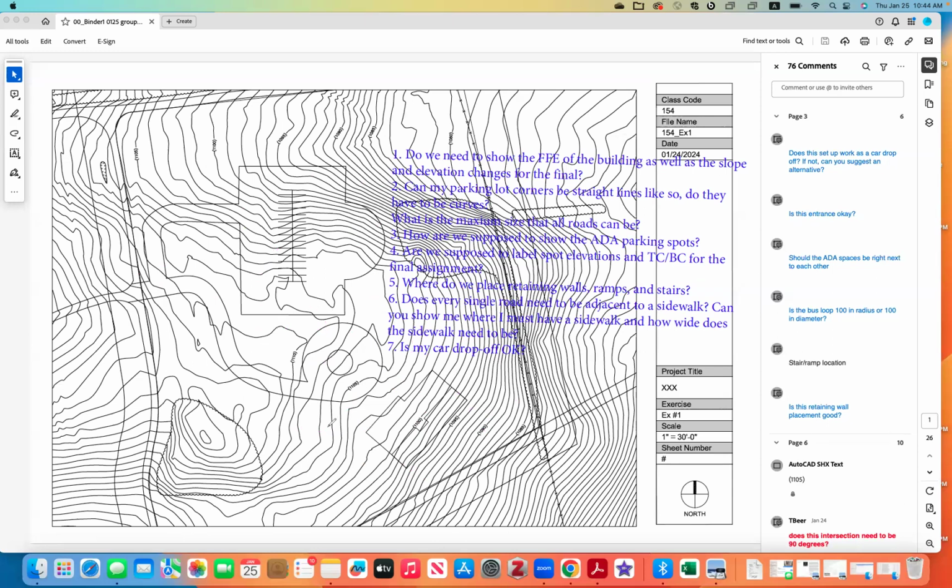How small does the little circle inside of it have to be? So you would base that on the width of the road. The road needs to be for bus turnaround. Do you remember? 30, 35, okay? And then based on that, you would offset your inner circle.